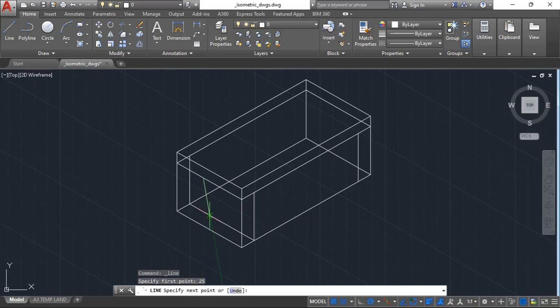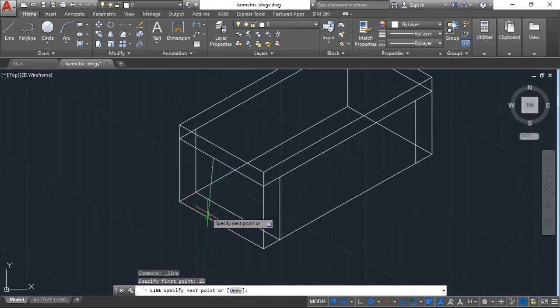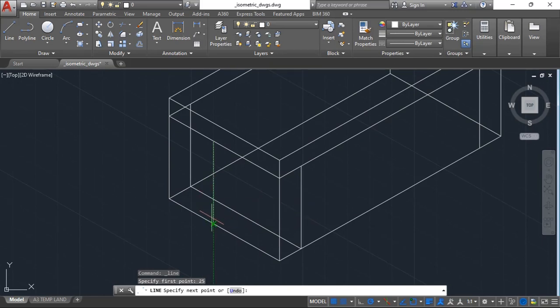and it should, okay, this is a little bit tricky to do, so what I'm going to do is to draw a vertical line here, and now draw a line which is at an angle of 30 degrees. It should intersect with that one. So along this I'm going to move 12 millimeters. So I should be able to move 12 millimeters to get that end point.